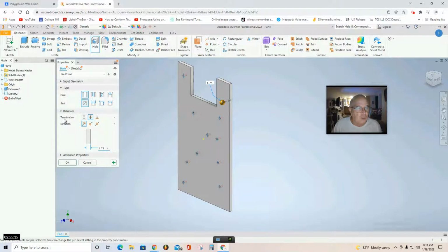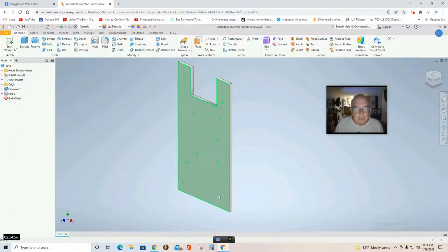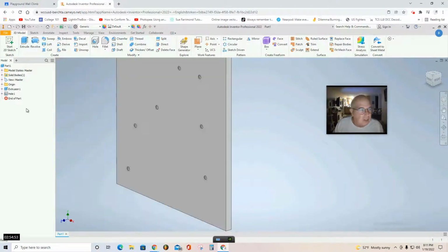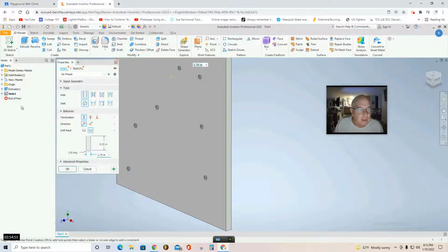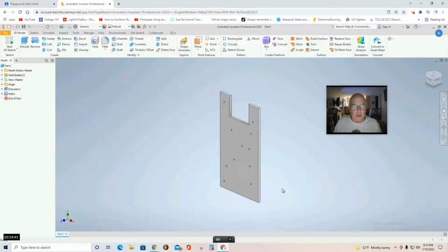And if you go with the termination, you'll select the first option, distance, click, and you should get an option to put the depth. Here it shows the depth. So I want to change 1 inch, which is the default. I want to enter point with a 0.25. Click OK. And I believe, I'm going to double check that. Yes, it should be 1.75 inches in diameter and 0.25 inches in depth. So it's okay. Now, there's nothing more to do but color it.